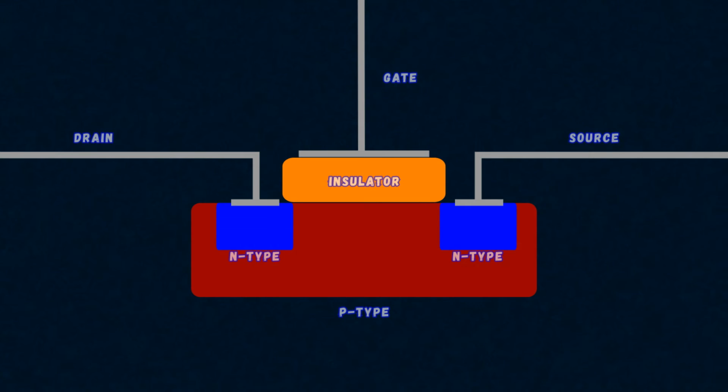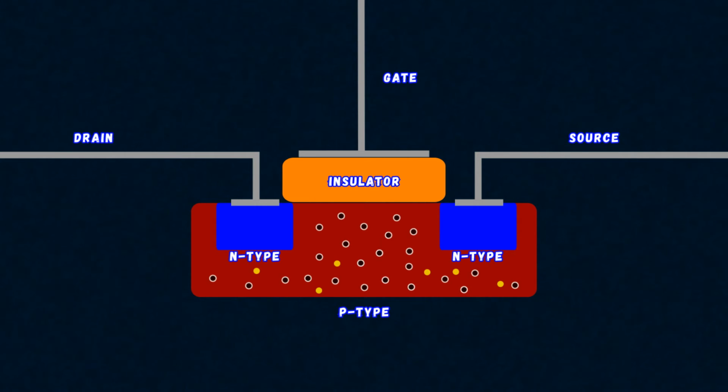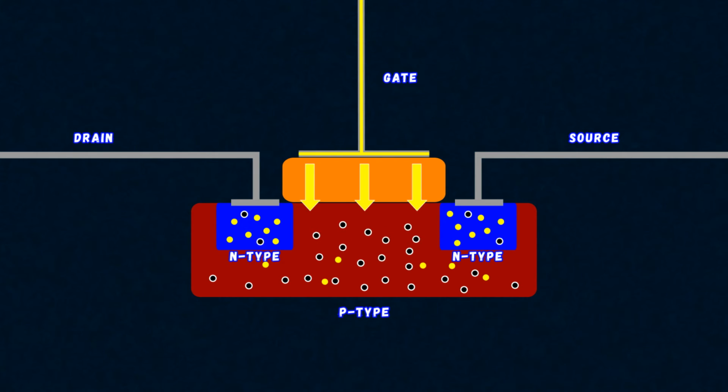A layer of dielectric, or insulator, is placed between the gate and the semiconductor. In the P-type semiconductor, the main charge carriers are positively charged holes, although there are also some electrons present. In N-type semiconductors, on the other hand, these functions are performed by electrons, although holes are present in them. Since the charge carriers in semiconductors of different types are different, our semiconductor assembly will not conduct current just like that.